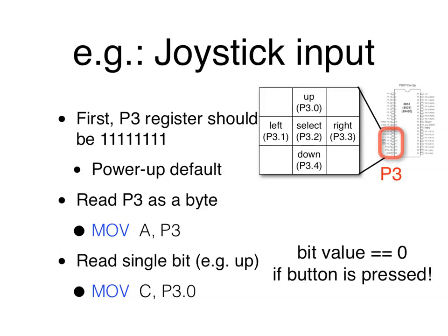Remember why ones? Because that is what allows it to go to pull-up mode. If you set it to 0, then it pulls it down low, and it's impossible for the button to override that value. Whereas if the GPIO pin is set to 1, then that allows the button to either remain at 1 or pull down to low, right?